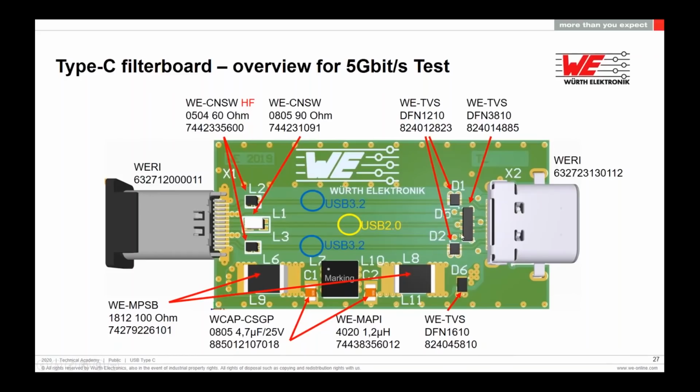And here we have a bigger one, which provides you easier implementation because you only have to place one part. Important for these parts is that you can easily put them on the microstrips because you can route through the parts directly without any angles. And this is very beneficial from an RF point of view.